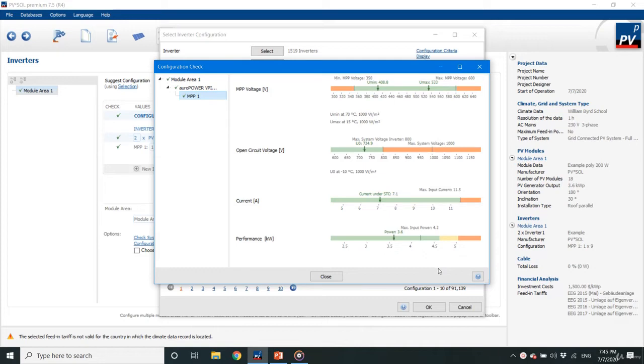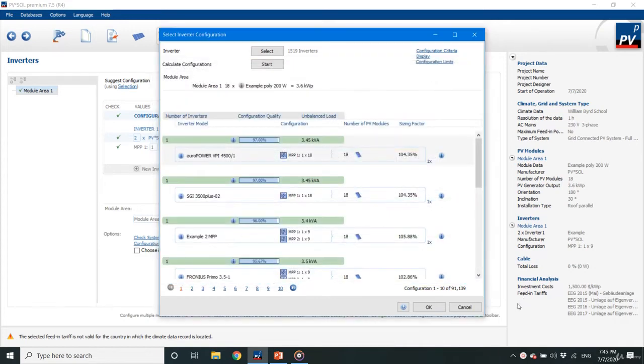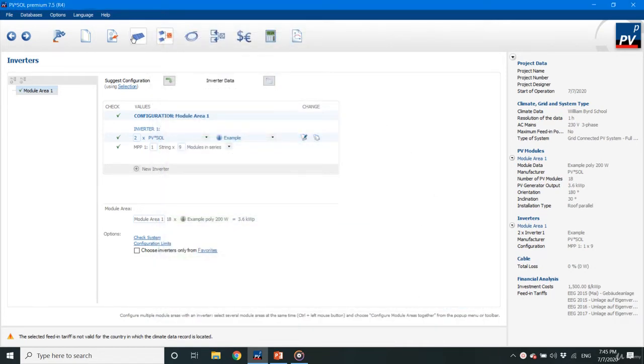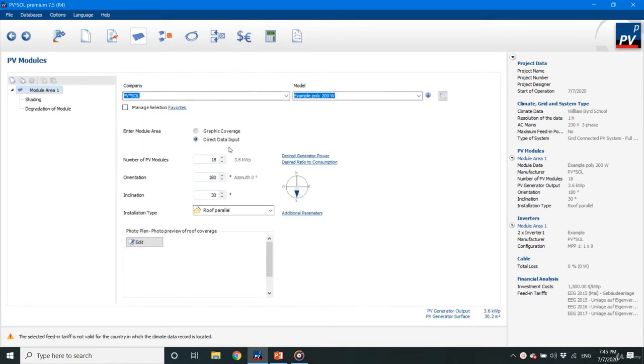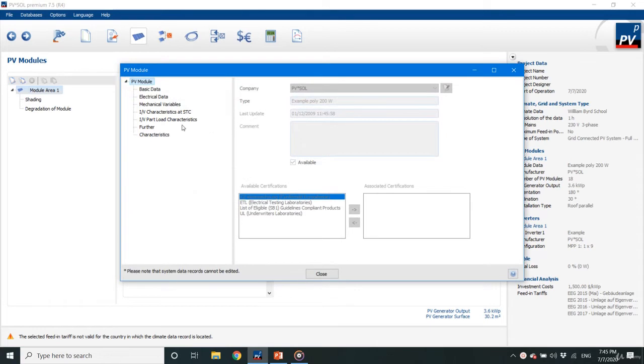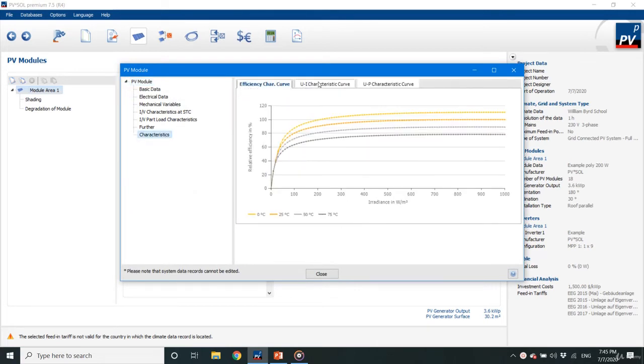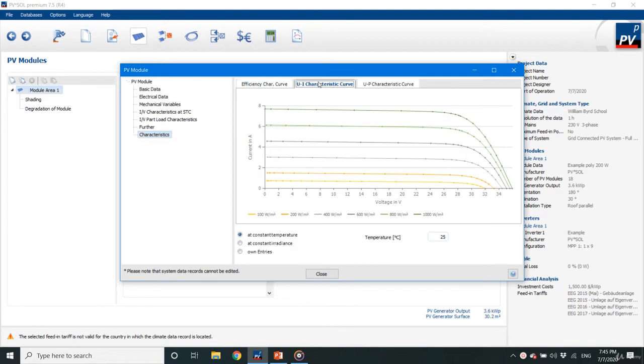Minimum voltage is again the voltage at the rated output current. The rated output current is 7.1 ampere. It makes sure that even if the maximum output of the PV modules is obtained, the voltage at 15 degrees Celsius, 1000 watt per meter square, and 70 degrees Celsius, 1000 watt per meter square does not exceed the tracking of maximum power ratings in the inverter MPP channels.